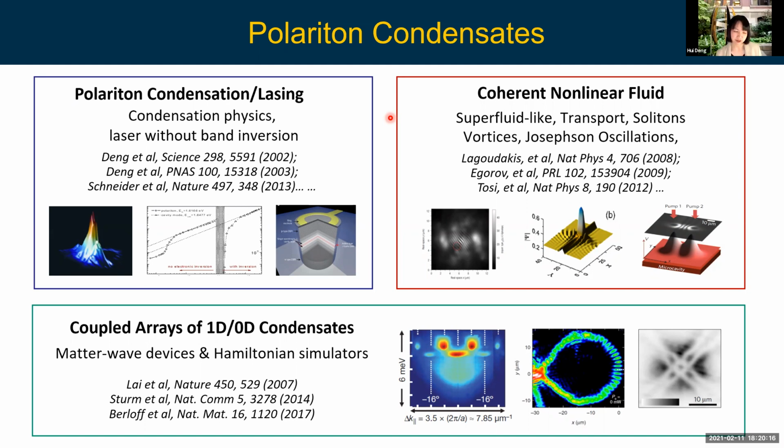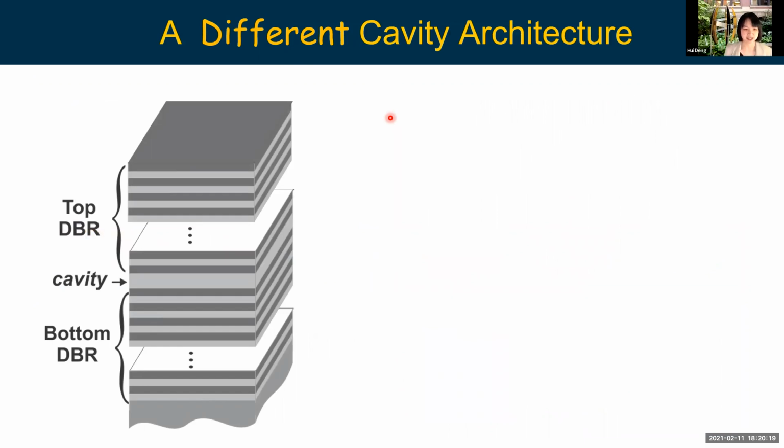Along those lines, one of the things we focused on was to see how we can better control those polariton modes. Typically, we have to bury the quantum wells inside a cavity, and we have to make everything perfect to reduce the dissipation and decoherence, to really go to the coherent limit. The cavity is grown by molecular beam epitaxy in a monolithic structure, and the mirrors are made by a huge stack of alternating half-lambda pairs, which we call distributed Bragg reflectors. So that makes it difficult to control the properties of these modes.